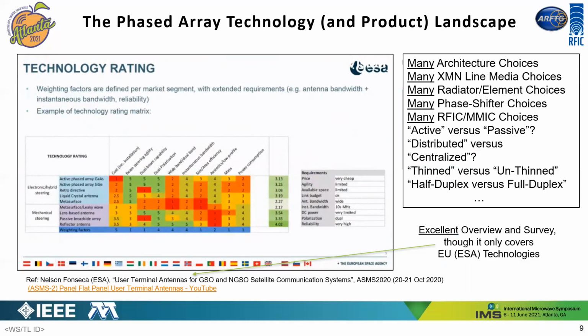Phased arrays are also termed half duplex or full duplex, depending on whether or not they use separate or common apertures for transmit and receive functions. Full duplex allows for simultaneous transmit and receive data streams, whereas half duplex systems have a common aperture, receiving 60% of the time and transmitting 30% of the time, typically, and using about 10% of the time to switch between the two functions.